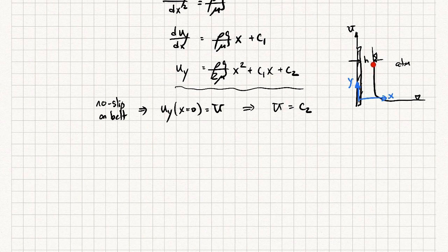If the liquid is moving upward on that surface, then the atmosphere has to move with it from the no-slip boundary condition. The no-slip boundary condition holds both at solid boundaries and fluid boundaries. So right at this free surface here, the liquid and atmosphere have the same velocity. Unfortunately, we don't know what that atmospheric velocity is there, so we can't really make use of it.